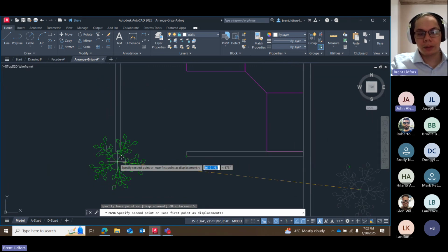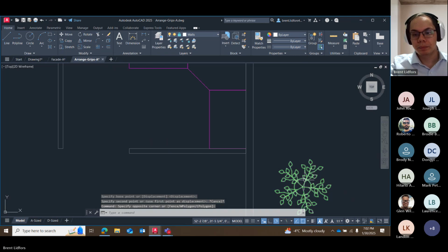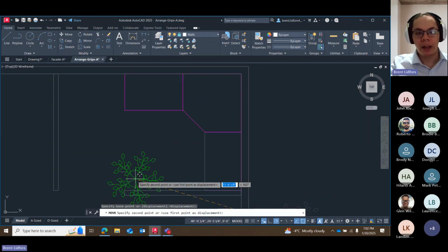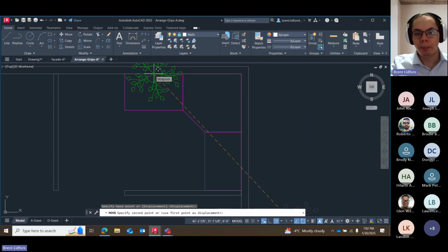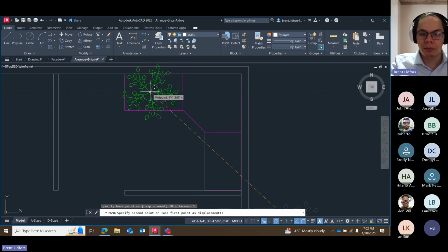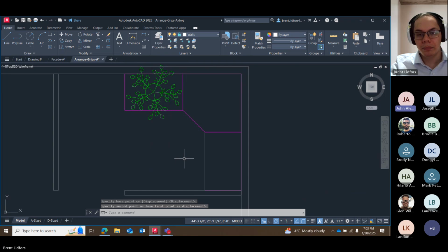Oh yeah, I haven't had snap tracking on, so that probably makes the difference. Yeah. And then from there, I just take that plant and I highlight the midpoint on the top or the bottom, either or, and then the midpoint on the left or the right. And then tracking both of those two together should give me the center. Perfect. Thank you. Yep, no problem.